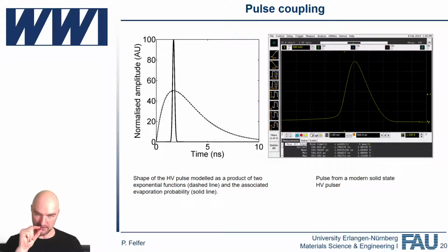You need to have an electrically very well matched system, so you don't get any pulse reflections in the system. But you can buy that stuff. You don't have to worry about that all too much. You just have to buy it so that it can withstand a kilovolt pulse, because usually data communication where these cables are used is not kilovolts, but rather single digit volts. But because our pulses are so short, mostly they're actually fine with that transmission.